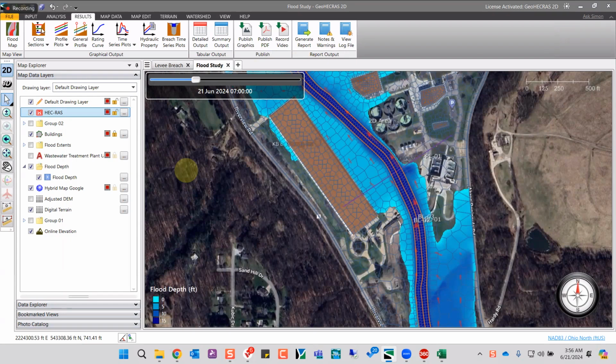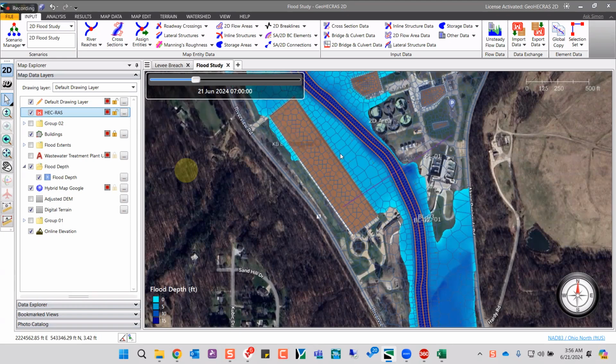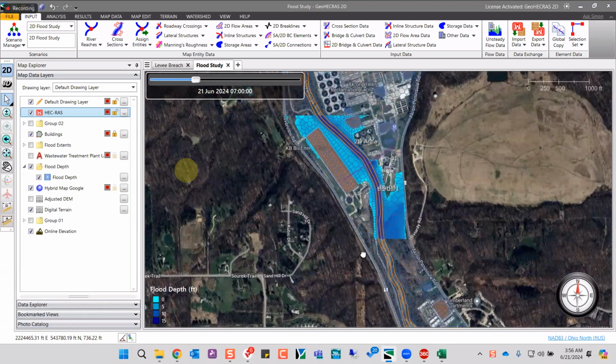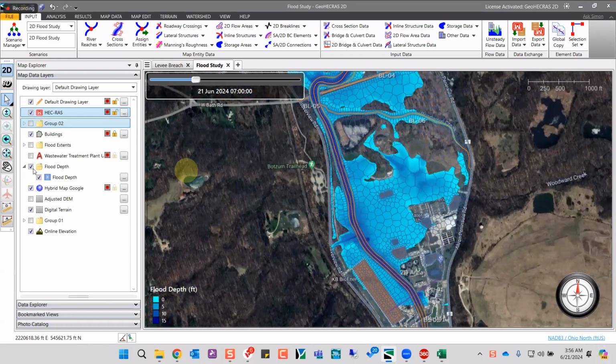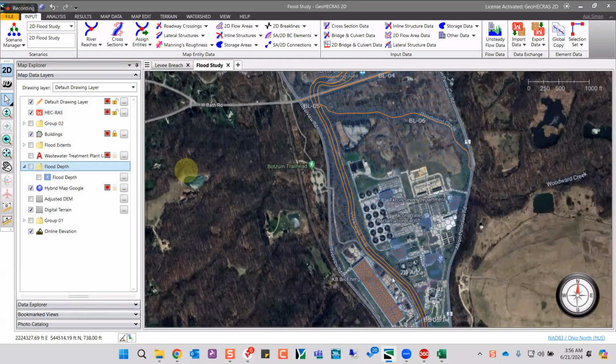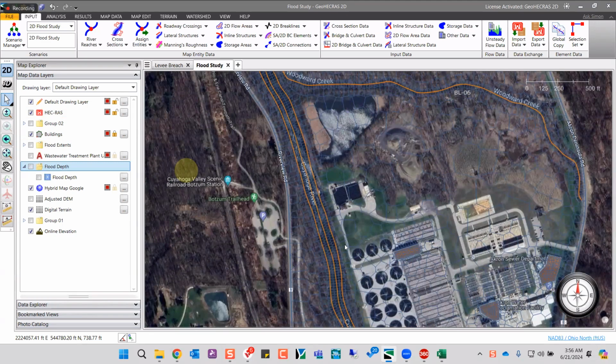Now, one of you mentioned hybrid models. If not required, do not use hybrid models. There are rules to define your hybrid models, wherein you can combine your 1D element with your 2D model. You have, again, a set of rules that you need to follow. Now, in case you have your river and cross sections define this area as your 1D model, and overbanks as your 2D model, in that case you will use your lateral structure to define the connections between your 1D model and 2D model, just as you did for your storage area.